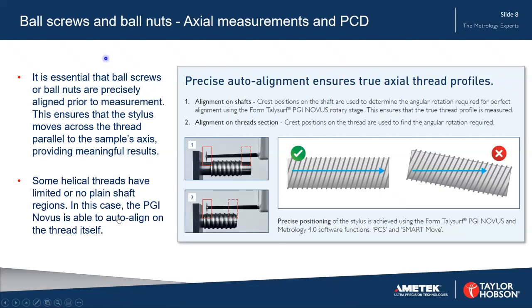Moving on now to another example of pitch circle diameter measurement on a ball screw. But before we can measure the pitch circle diameter accurately, we have to make sure that we've aligned the ball screw to the traverse unit, to the direction of the measurement.